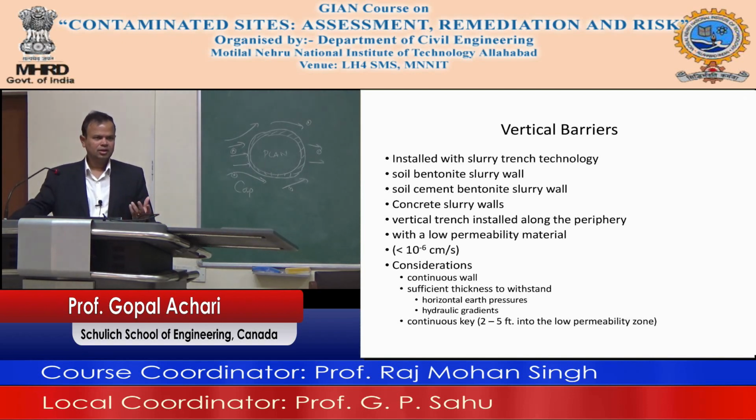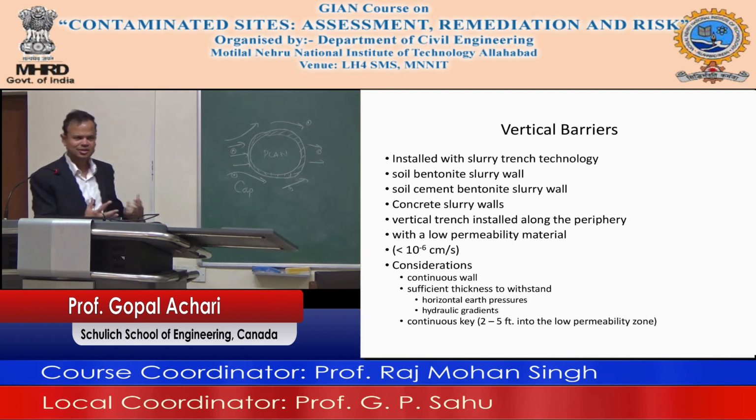So the characteristic of bentonite is, add water to it, it will become like jello in a way. Now jello has no strength, right? You know what jello is, right? Jelly in a way. So it has no strength. If you put it there and it dries, it will all crumble, everything will be gone. So you need to mix it with soil. So you masticate it nicely.